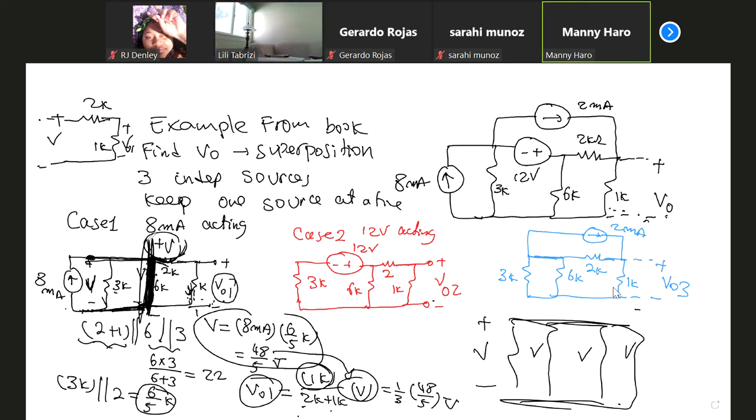Professor, is this because the current is not going to be the same since 2K and 1K are now in series? No, they are in series, the current is the same. Because remember, this end doesn't go anywhere. This end is open. Okay, thank you.